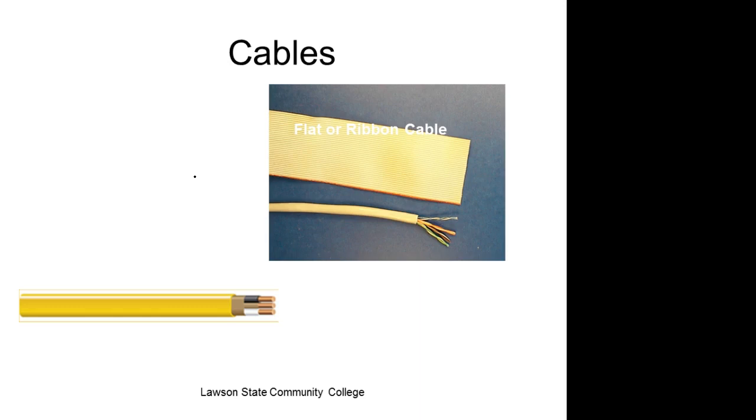You would say this is 2-wire with a ground, so this is your ground, this is your neutral, and this is your, what they call a hot lead. NEC calls this lead right here the ungrounded current carrying conductor. They call this the grounded current carrying conductor, and then this is ground. So if you ever looked at your box, the neutral is connected to ground.